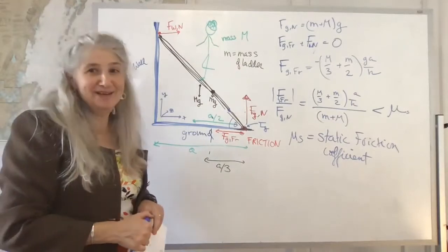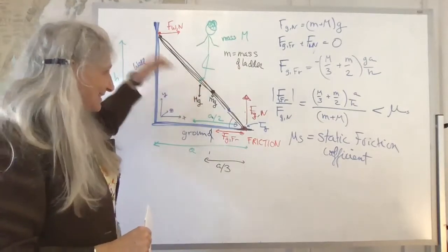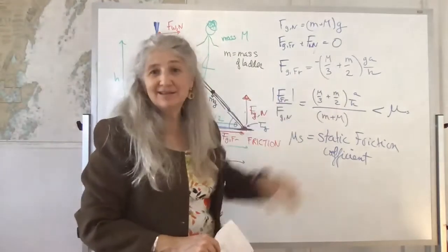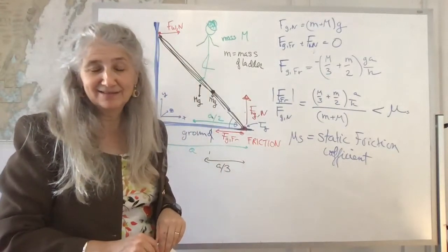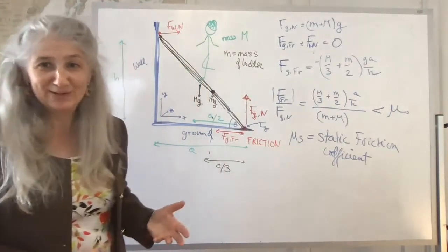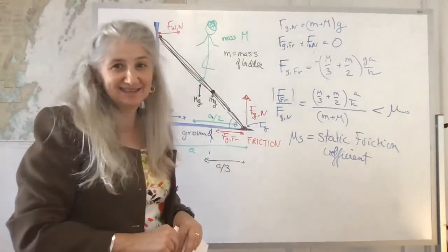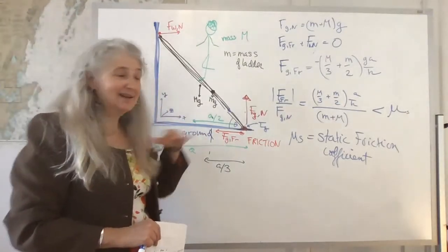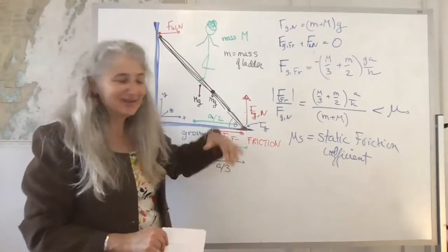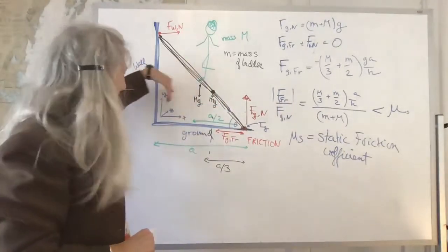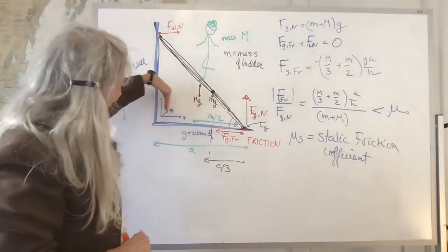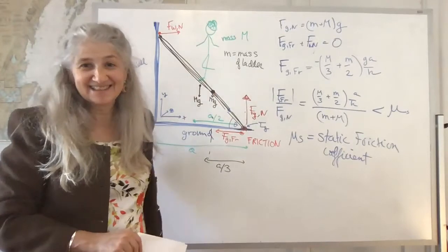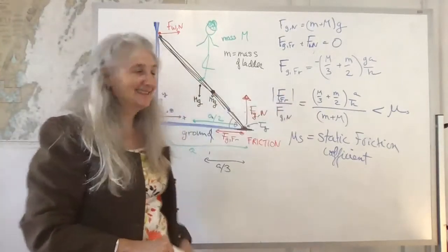And so the requirement on friction: if you tilt the ladder over, A gets bigger and H gets smaller, and so the required friction force would obviously be larger. You need a larger friction force to keep it from slipping. Intuitively, if you put the ladder up steeply, at a larger angle, so it's more vertical, it's less likely to slip. So that is consistent with this setting.